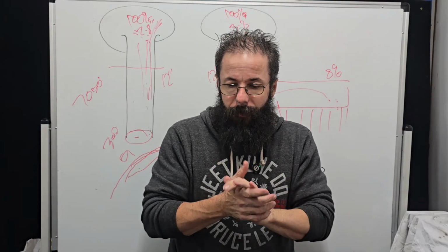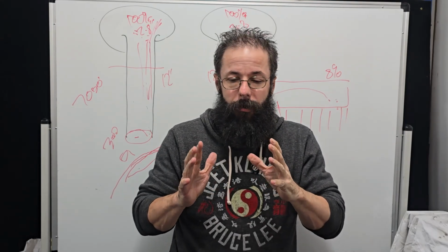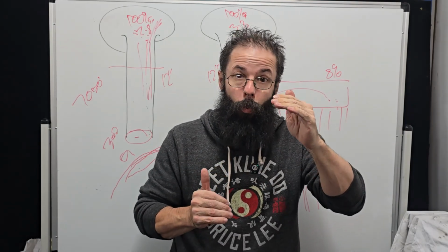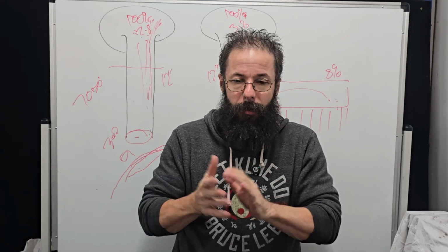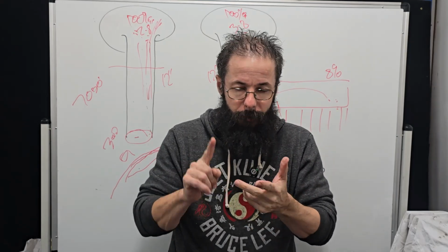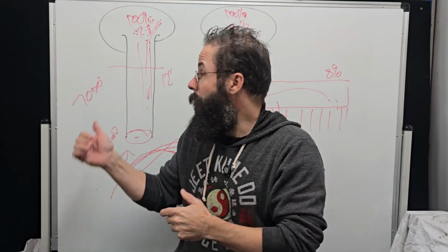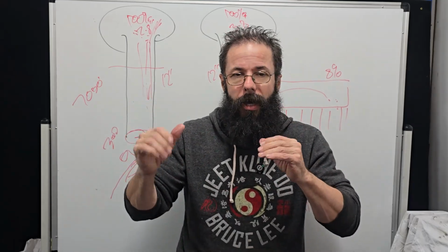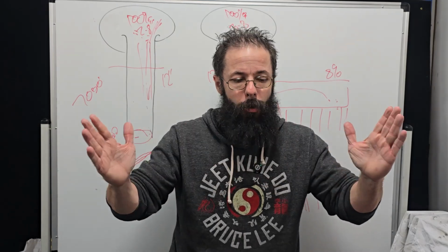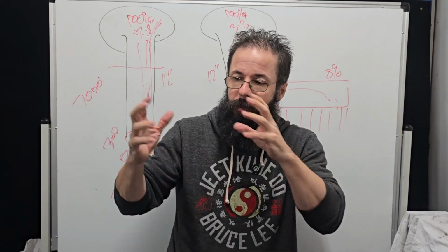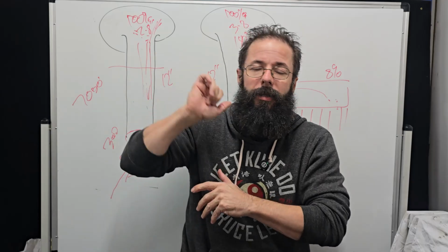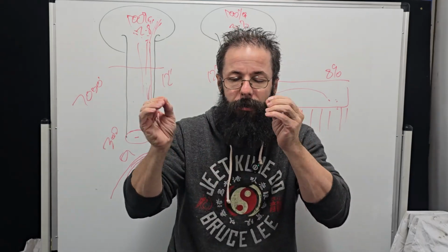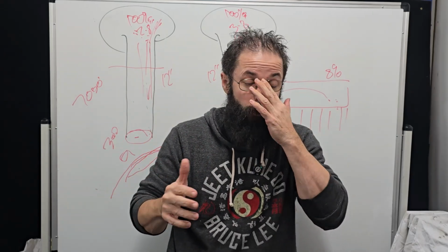But yeah, that sort of thing really annoys me in one way, because it's giving guys not a good idea of what is optimal runner length, because you're using a parallel runner, which is more restrictive. We have a thicker boundary layer. We have higher averages. So you're changing all that. This is why we've got to look at the total induction length, the averages, the plenum, the wake, the airspeed at the top of the plenum, because all these little things change your end result and won't give you good feedback.